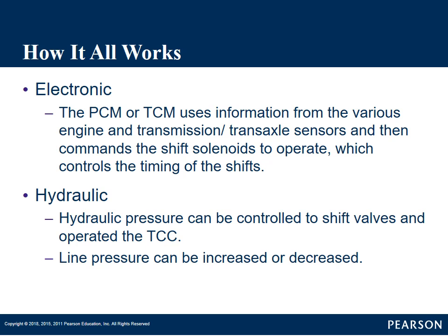When we went to downshift, throttle pressure had to overcome governor pressure so we could downshift, say we wanted to pass somebody. So in a hydraulic transmission, we had throttle pressure and governor pressure to determine when it shifted. In an electronic transmission, we are using sensors and switches to determine when that transmission shifts. Okay?